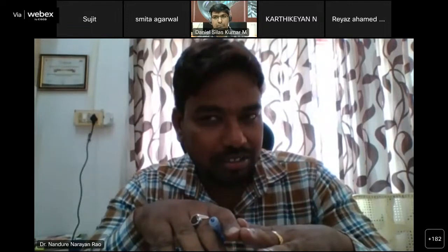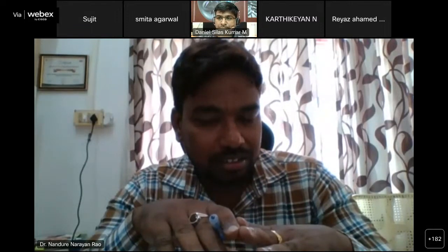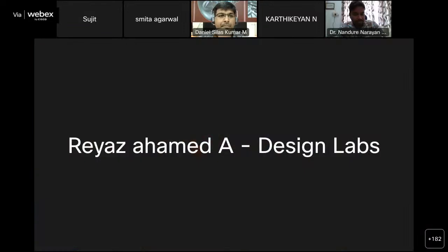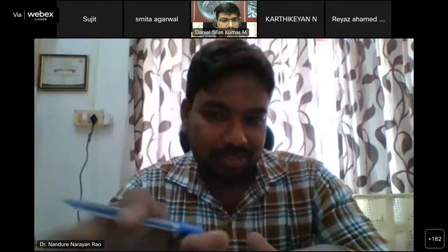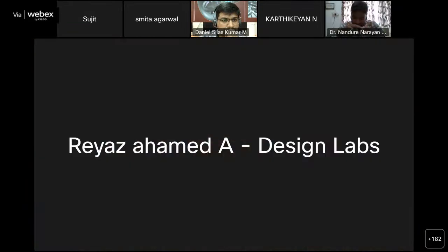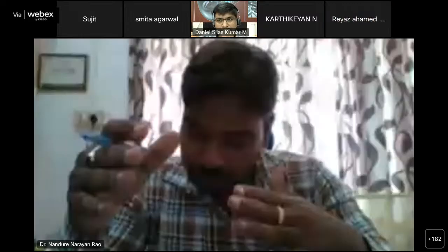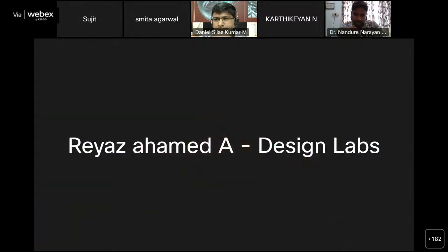Yes. In Fusion 360 itself, we completed all the analysis. If finite element analysis is what you need, the structural or thermal analysis you have done is FEM. My basic doubt is what element type we are using, because in ANSYS we can define the element type. In Fusion 360, the element type is tetrahedral, sir.